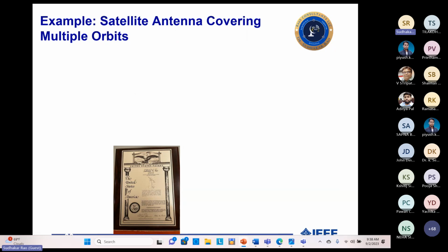So this is a typical example of one of my patents. What is the novelty in this case? Before, there used to be different antenna designs depending on the orbital slots to cover certain regions, going from 70° west up to 120° west orbital slots. Every 2 degrees, one slot, right? So people designed differently because the shaped coverage area changes based on the orbital location. So this particular design covers a complete orbital arc. One design basically covers all the orbital slots.